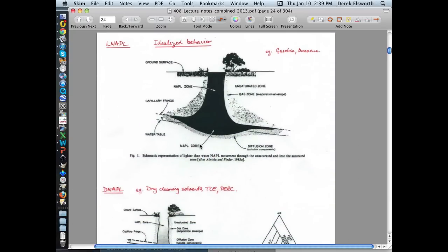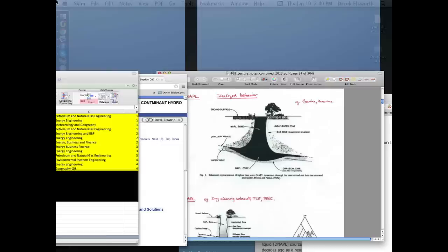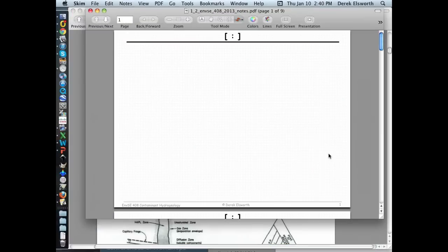But we made the case last time that we're choosing to deal with solvents in groundwater, non-aqueous phase liquids in groundwater, gasolines and diesel fuels, which are lighter than water and float, solvents such as TCE and TCA, which are denser than water and sink through water. And the behavior that we're interested in is conditioned by the behaviors of these components in groundwater.